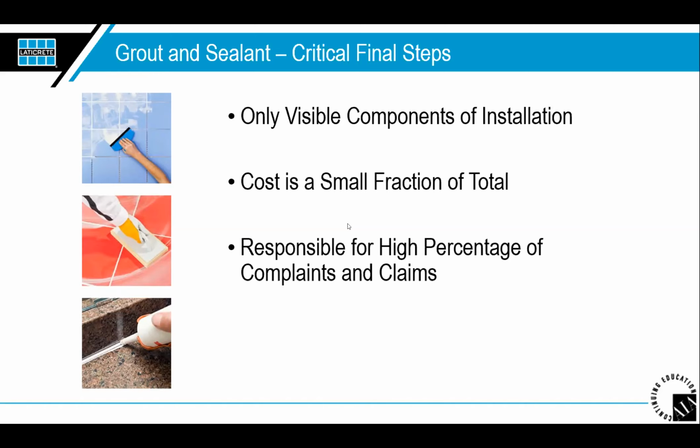Regular sanded, unsanded, I mean, not the improved versions, but because they think it's just easier to install. But when you look at regular sanded grout that has a porosity rating of 10 to 15% versus a type of epoxy grout that might be 0.5% or less, you're really giving the customer exactly what they're asking for whenever you're talking about something that's durable, something that's nice and hard, that's not going to wipe away, something that stays clean longer, right?